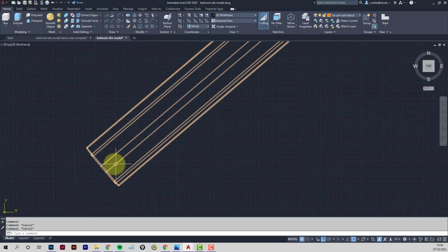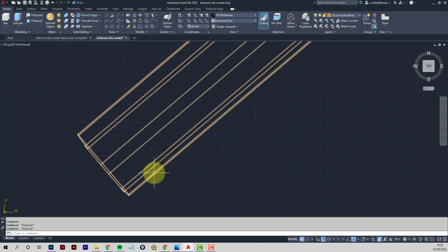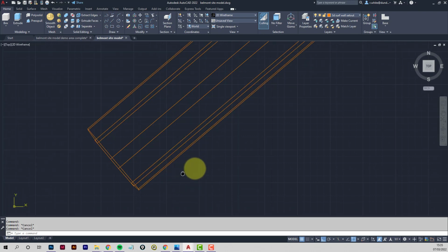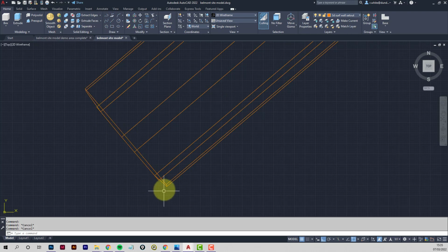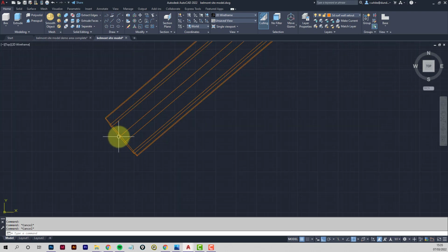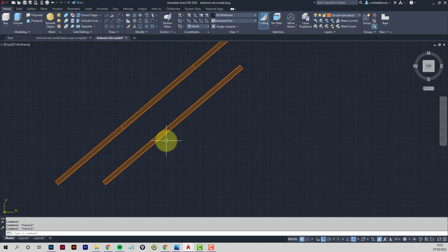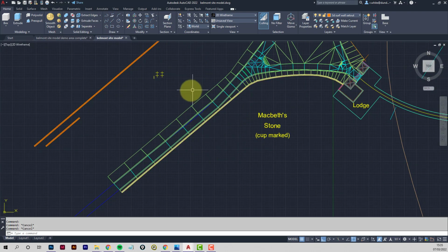It's not very slopey. But if you've got a more pronounced profile of the ground, then the tilt can be pretty disastrous. Okay, you can see the end of the wall. We can make out the end shape slightly. It shouldn't be visible. So what I'll do is, instead of sweeping, which is okay, what I'm going to do is loft instead.